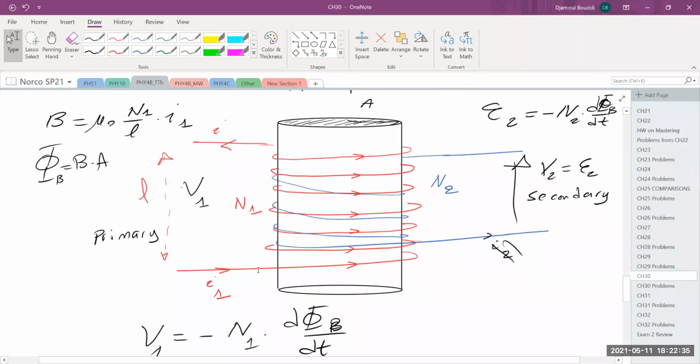And even if you unplug it from the computer and you have it just plugged into the wall, it stays hot because there is a current running through the primary still, okay? Although the secondary, in this case, has no current in it because you unplugged it from your phone or from your charger, from your computer, whatever that is. So there is always current in the primary in this case, albeit in here it's disconnected. Although modern chargers have this safety feature in here. If they notice that this is disconnected, they disconnect the current in here immediately, okay?